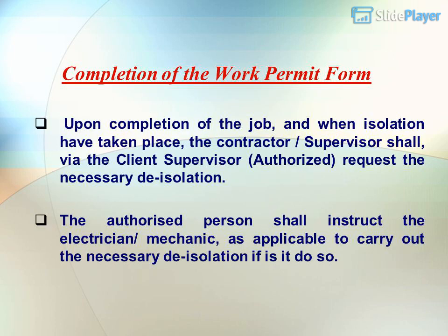Completion of the work permit form. Upon completion of the job, and when isolations have taken place, the contractor supervisor shall, via the client's authorized supervisor, request the necessary de-isolation. The authorized person shall instruct the electrician/mechanic, as applicable, to carry out the necessary de-isolation.